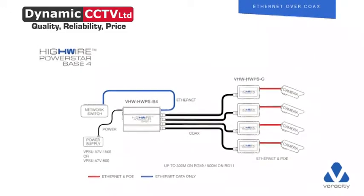This is not powered by PoE. It's powered by 2 different power supplies. You choose which one you want, depending on the wattage, again, as I said, for what you need at the end point. So you'd have a data connection from the switch into the Powerstar. That's a gigabit port that's on there. We've got a fibre SFP on the back of this as well, if you want to use fibre across your network. And then obviously you've got your 4 coaxes going into your Powerstar, which are in the back box of your camera, and they'll in turn power your camera.